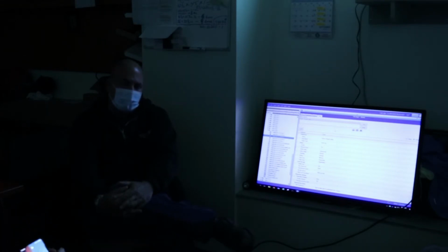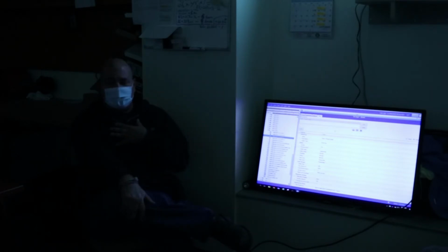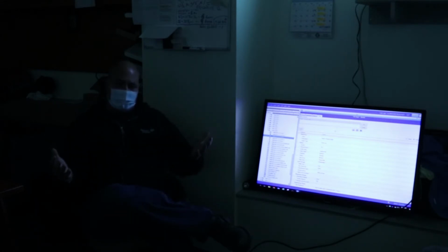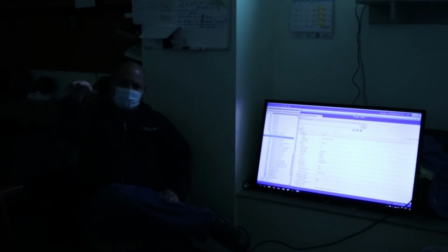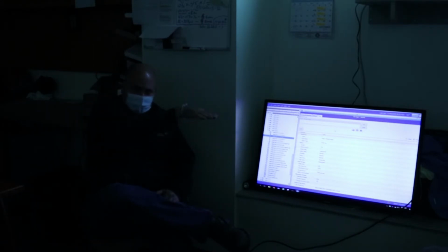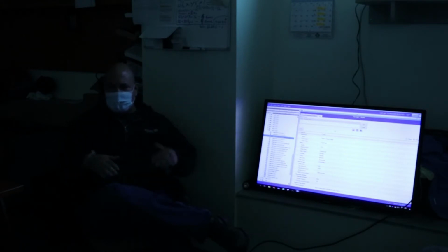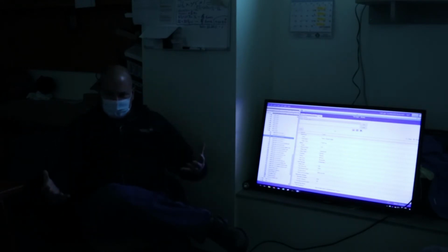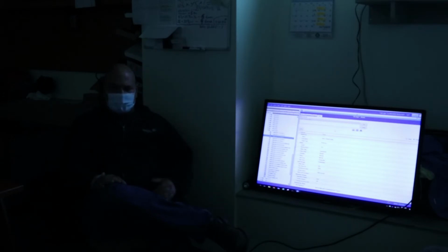So, I haven't looked at it, so I can't necessarily speak for it, but it can be sped up. Generally speaking, in the controls world, slow is good, right? Because there are two scenarios you're going to have. You're going to have a gradual increase or decrease getting to the point you want, or you're going to go up, down, up, down, up, down until you level it out. But for a tuned machine, 2 hours seems a bit excessive to make 5 degrees.